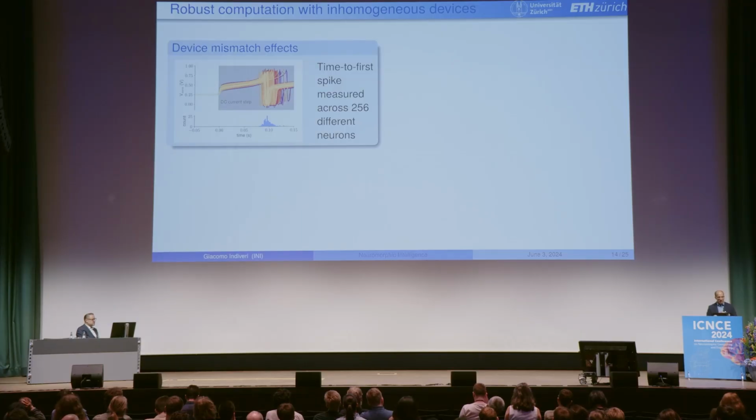In fact, without trying to optimize for reducing mismatch, just by making adequate circuit designs, with a compromise between making them small but also not too noisy, the typical variability that we get is about 20% coefficient of variation. So the standard deviation over the mean is about 20%. Can we do anything with this? I would never put this in an airbag controller or in an Excel sheet to control my bank account. So is there a way that we can actually use it to do something accurate?